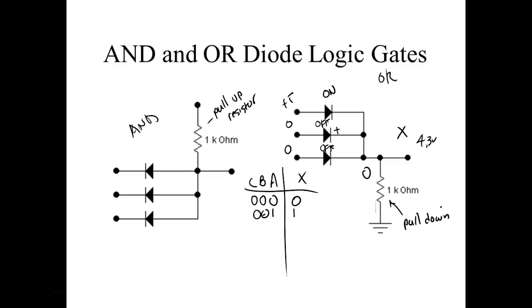Okay, so imagine the diode. We know it's not exactly an open switch, right? You understand? But we can talk this way. So let's say I come over here and I have a switch, and then I connect that directly to plus 5 volts. And then I close that switch and this right here goes to ground. Well, I just created a short circuit. Right? If I put a resistor right there, that means when I open the switch, then over here I get plus 5 volts. If I close the switch, that's going to connect to the bottom of that resistor, so here it would go to 0 volts. So that pull up and pull down resistor allows me to bring a true 0 in, or what?